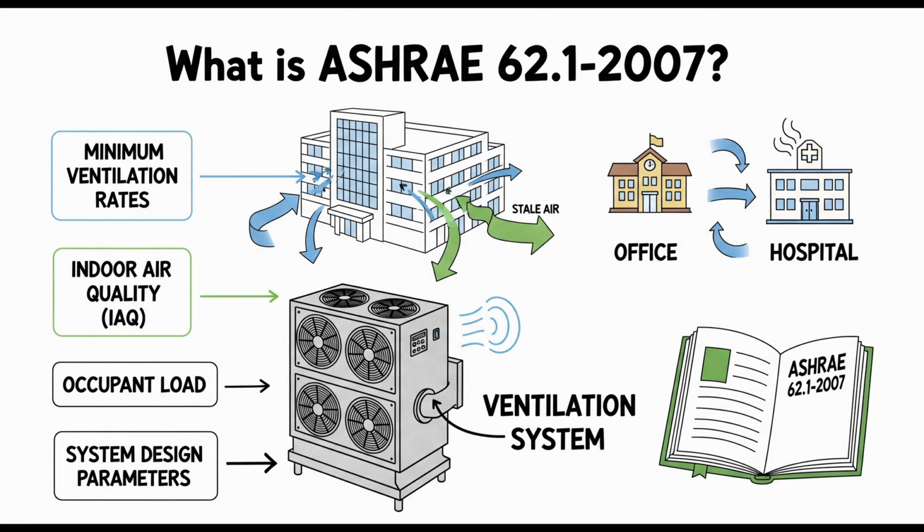What if you have one big air handler serving multiple rooms and it recirculates some air? Now you're getting into system ventilation efficiency, Ev, section 6.2.5.2. This one gets pretty complicated, especially with variable air volume systems and recirculation. Keep it simple. What's the core idea? The core idea is that when you have a central system mixing outdoor air with return air and sending it to multiple zones, not all the outdoor air you bring into the main air handler necessarily makes it as fresh air to the worst-case zone at any given time.